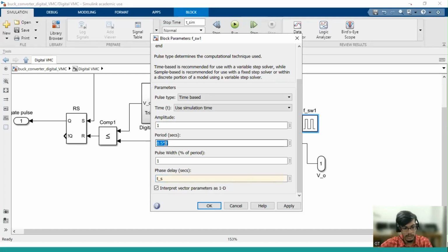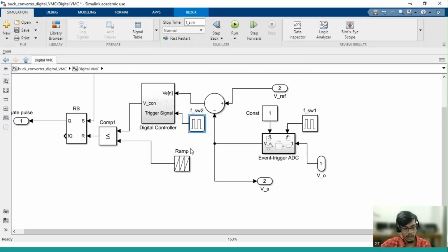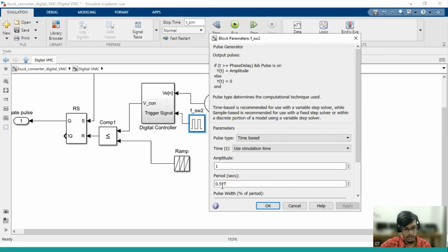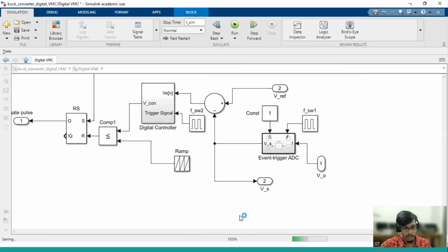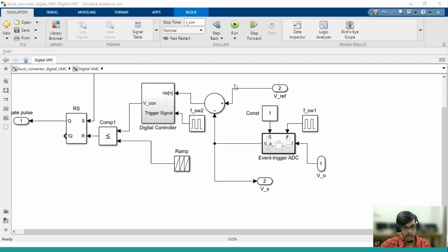I understood that the simulation does not change, but now we change the sampling time to 2T. So if we go to hardware, as you showed, while we are taking the sample just before the switching, that one time is 0.2T in the last case. So now we are taking 2 times, which means the delay will be increased to 0.2T. Can you draw that and show?